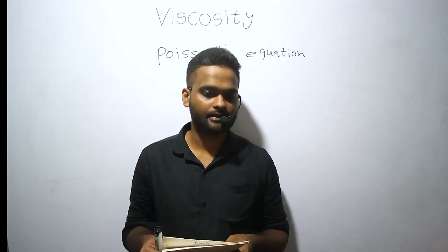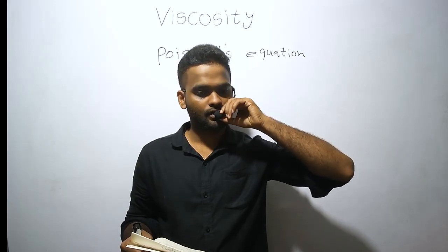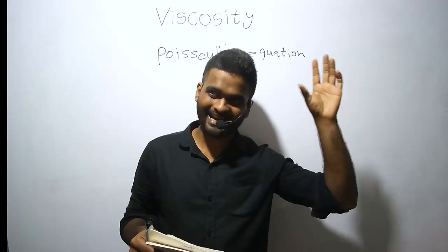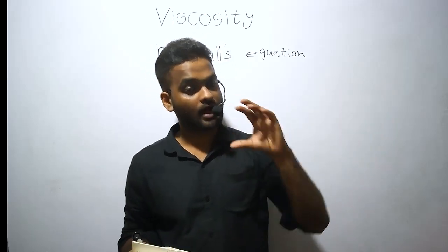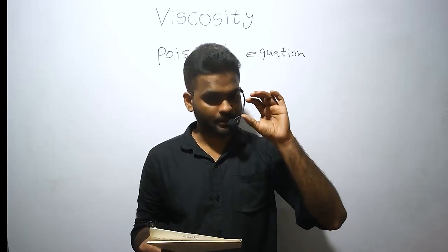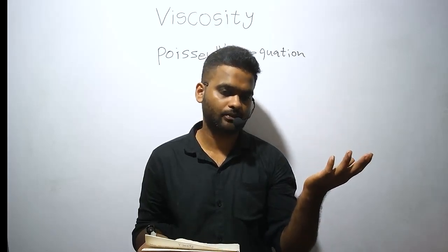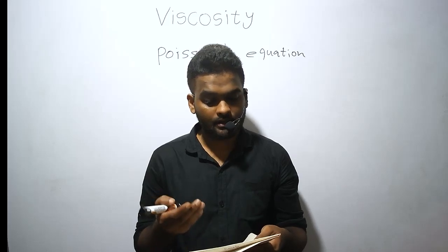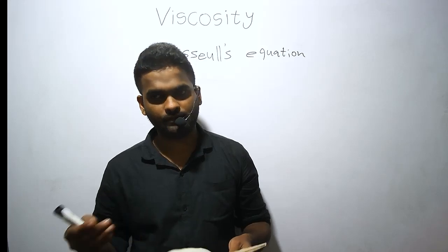Right? So here, this Poiseuille's equation, right? You had Bernoulli's equation, but that Bernoulli's equation can only be applied for non-viscous liquids. For non-viscous liquids only, that Bernoulli, right? Remember? Because that's the energy equation, right? If there's friction, you cannot apply Bernoulli's equation. But here we are talking about liquids with friction, right? So we need another equation. You cannot apply Bernoulli's equation here for these questions, if it is a viscous liquid.